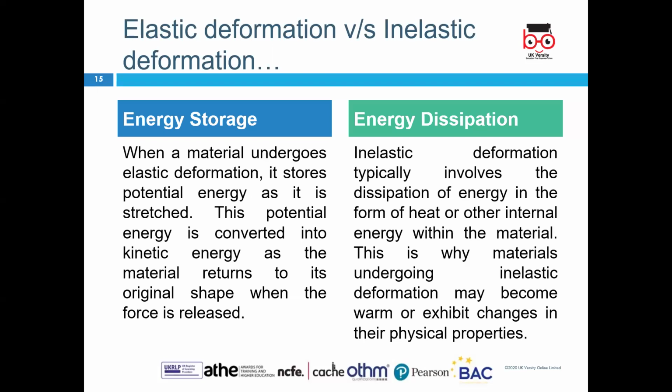But inelastic deformation involves dissipation of energy, where there is some kind of energy loss. This is why materials undergoing inelastic deformation become warm or exhibit changes in their physical properties. You don't have full energy storage in the case of inelastic deformation. There is energy dissipation in the form of heat or any other internal energy within the material.